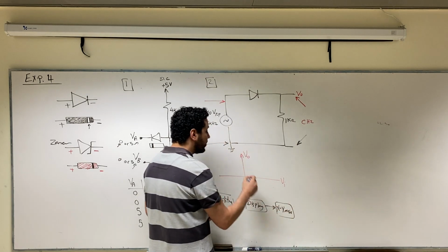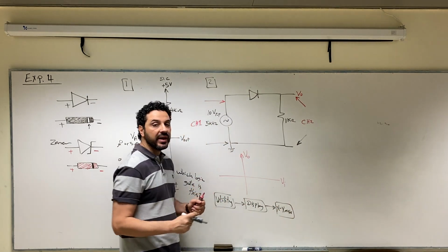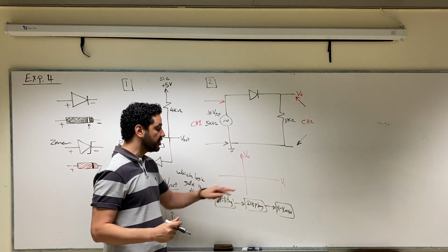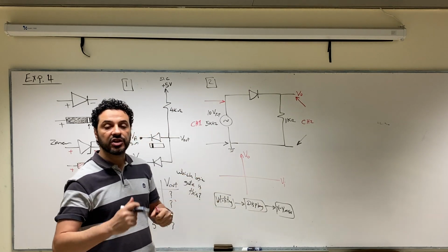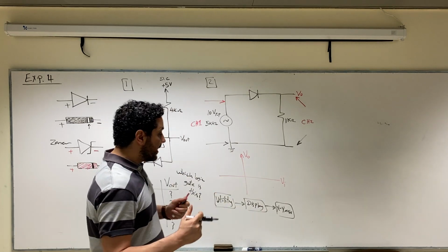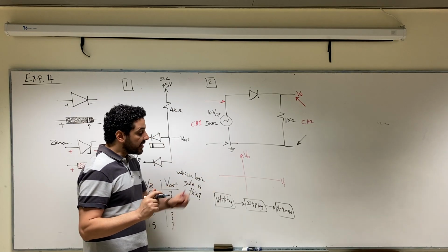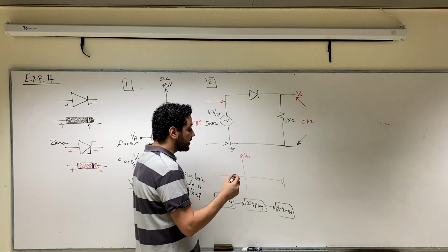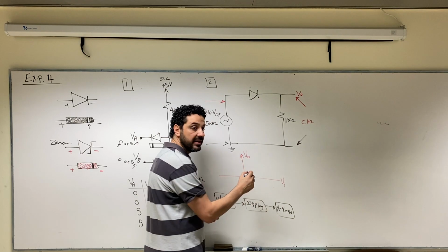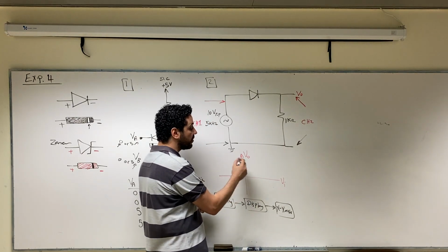The XY mode will give you a plot between channel 2 and channel 1. Channel 1 on the horizontal axis and channel 2 on the vertical axis. But when you use the XY mode, it's important to have the same voltage scale for both channels.